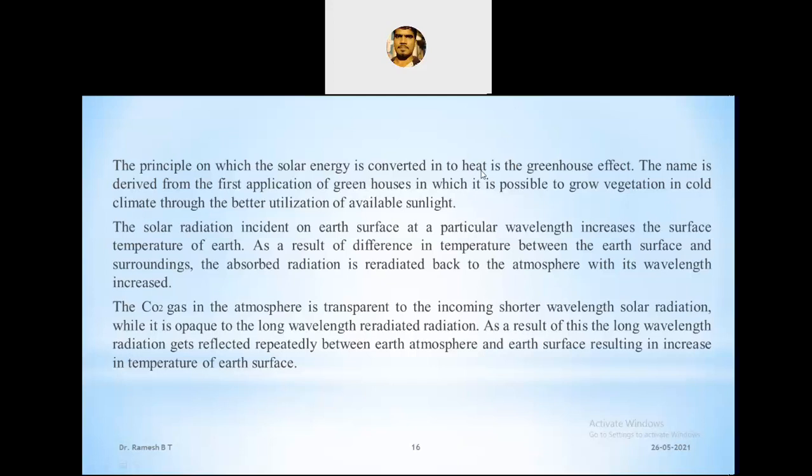We can also coat it with black paint, so that the black paint absorbs. We already know that black color absorbs energy and white color reflects 100% of the radiation back. So we can use this black plate to absorb incoming solar sunlight, under ordinary window glass. The black absorbs as a property of a black body, and ideal black bodies have not only the highest absorption but also the highest emission coefficient for all wavelengths of light.